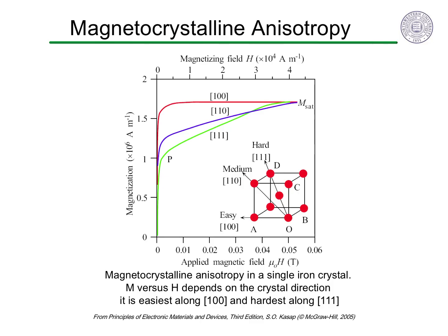In a crystal, the magnetization prefers to be along a particular direction due to magnetocrystalline anisotropy, even in a cubic crystal. For example, BCC iron reaches its full saturation magnetization in a small applied magnetic field when it is along 100. We call this the easy direction. Magnetizing along 111 requires an additional magnetic field to rotate the magnetization from 100 to 111. In iron, 111 is the hard direction. When the field is removed, the magnetization will rotate back to the easy direction.